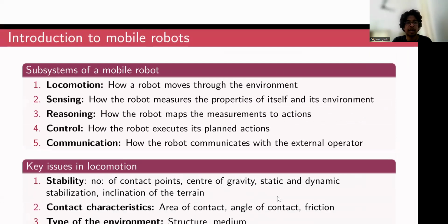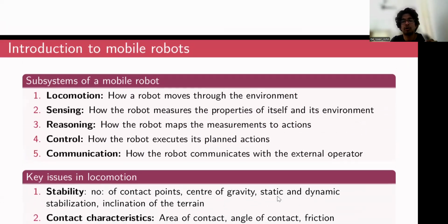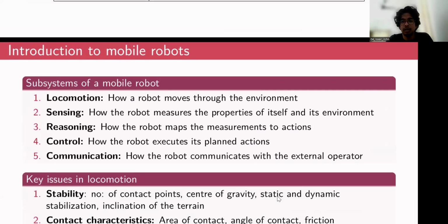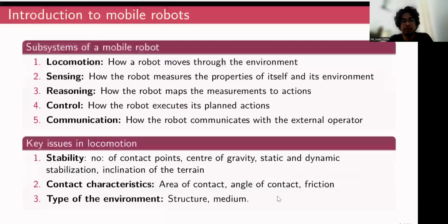And then the kinds of sensors that a mobile robot requires. They can be classified depending on the type of sensors we are using. In week 4 we saw two different classifications of sensors. Whether it is measuring something internal to the robot, such as the reading of the encoders, the battery levels, or the inclination of the robot chassis, all these things are internal to the robot. We call those proprioceptive sensors.